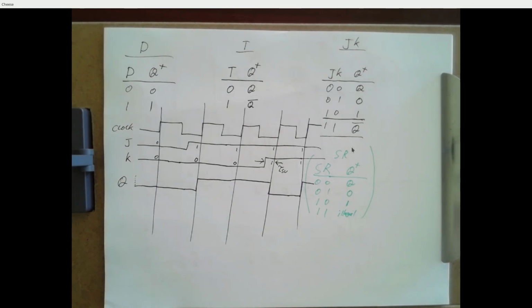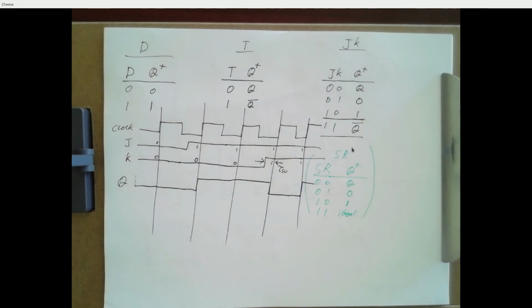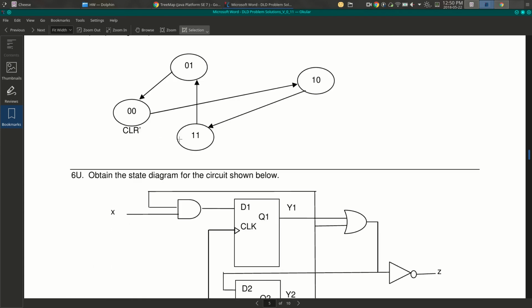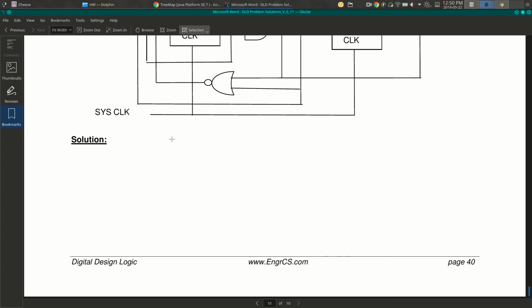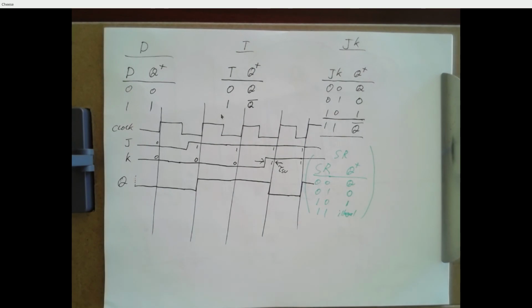The other problem is, right, these flip-flops have maximum speeds they can run at because of this setup and hold time, right? We have this circuit over here. When an output changes, it's got to take time to get over here, go through this inverter, come in here. It's not going to immediately go into D1. It's going to be delayed by the propagation delay of whatever circuitry you have. And if you have a big circuit like this, right, or a really big one like this, there's a lot of propagation delay. So setup and hold time will come into play when we say, hey, how quickly can we clock the system?